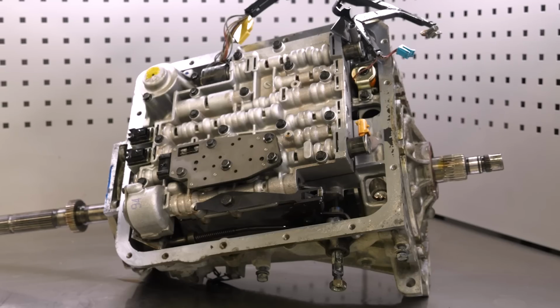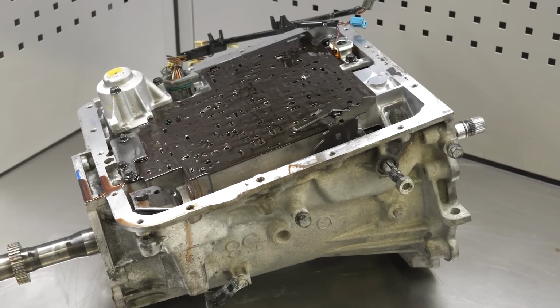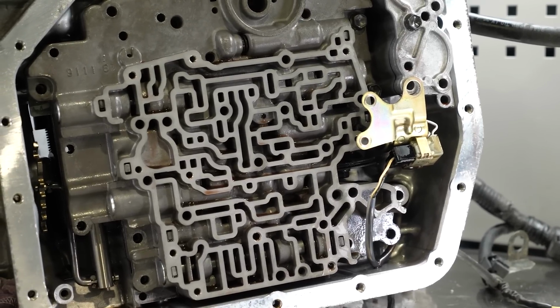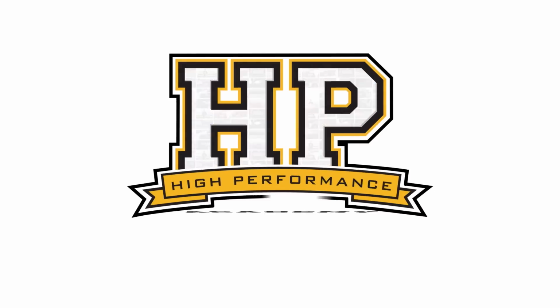After the torque converter, the next most important component in an automatic transmission system is the valve body. This isn't actually a single component, but an assembly of fluid passages, solenoids, valves, accumulators, wiring, and electronics that executes the control strategy we program into the transmission control module. There's a very broad range of complexity in components used in various valve bodies, and some have components I've not mentioned. But the truth is that we don't need to know every little part inside every transmission in order to gain serious improvements through calibration and upgrades.